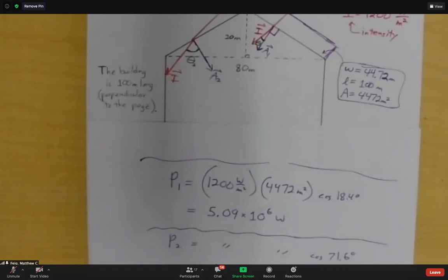They'd point south, but they would move from being kind of vertical near sunrise and sunset and tip back, slowly changing orientation, trying to stay perpendicular to the incoming sunlight throughout the day. There were some challenges with that, but you can see how it takes a little bit of energy to do that, but you absorb more energy over the course of the day than if you just sit at one angle that's considered optimal for that latitude.